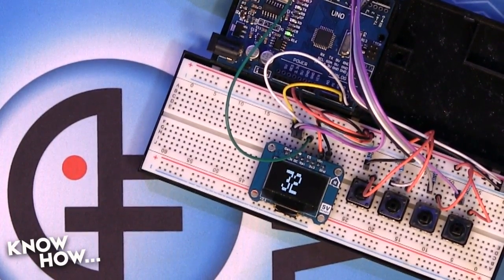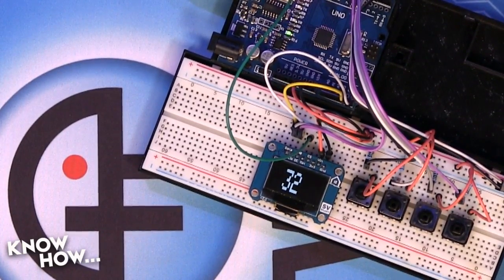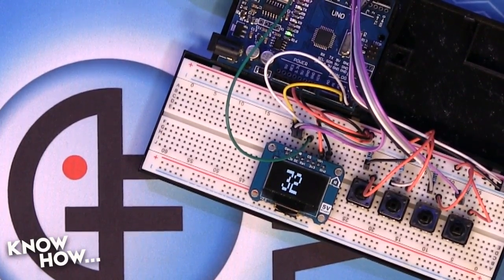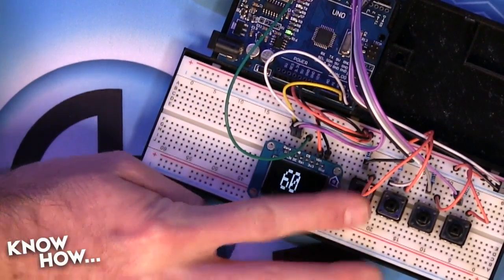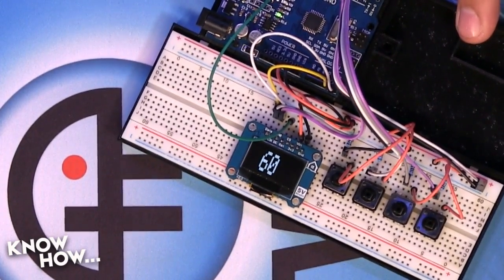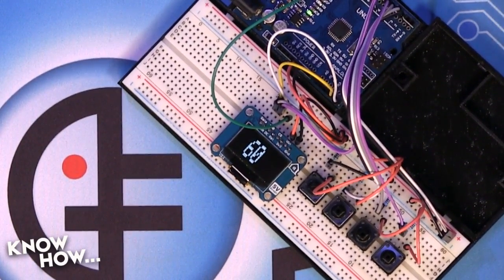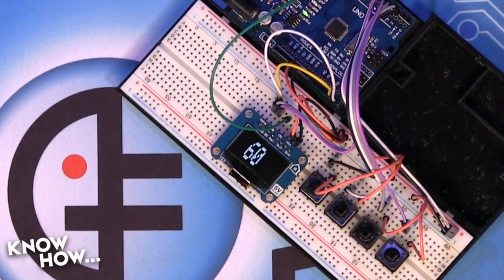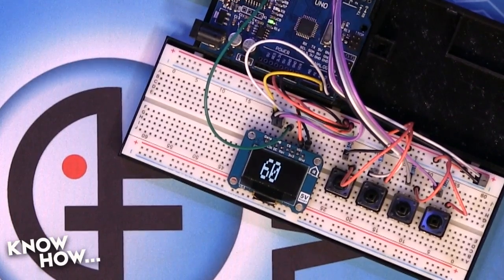Or, even worse, what if I'm using this to count how much nutrients to add to the water, and it keeps having a bug where it keeps browning out, and it just keeps resetting to 0 before it gets to the stop. You speak like a man who's gone through that before. This is not hypothetical. This actually did happen. What we need is a way to make sure that that value, whatever that counter is, is persistent. It stays after power off. Okay. And that's what we're going to use the EEPROM for.